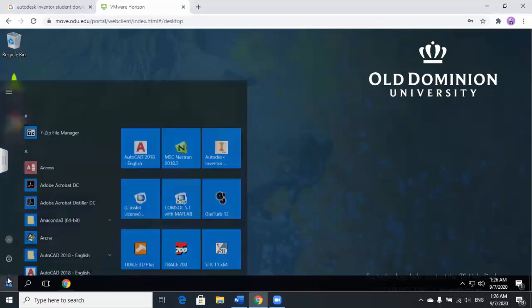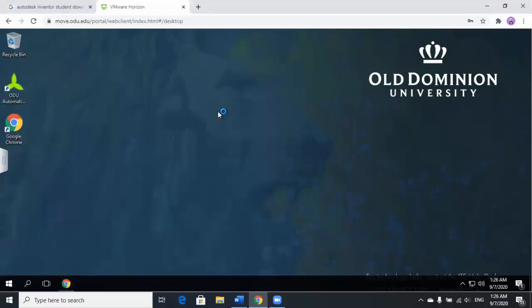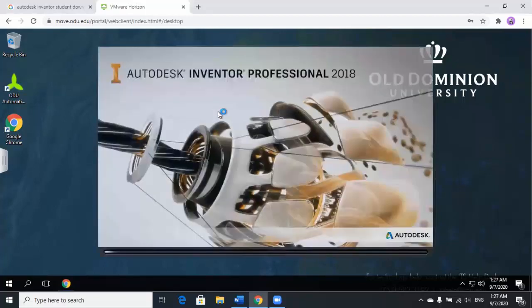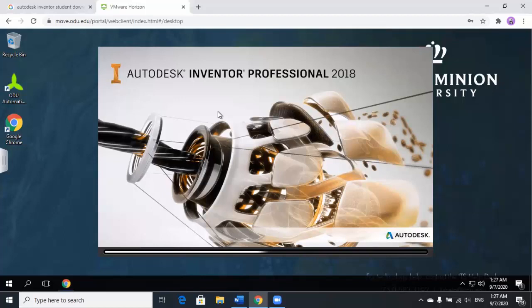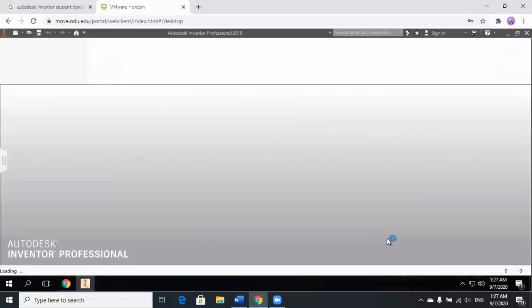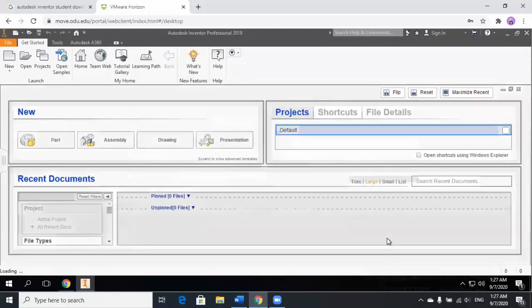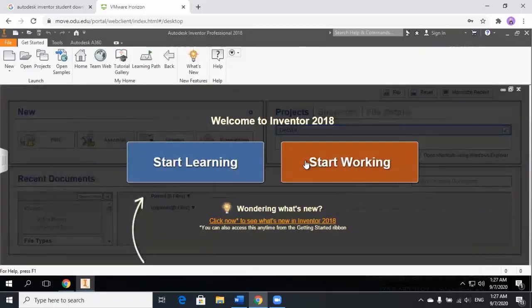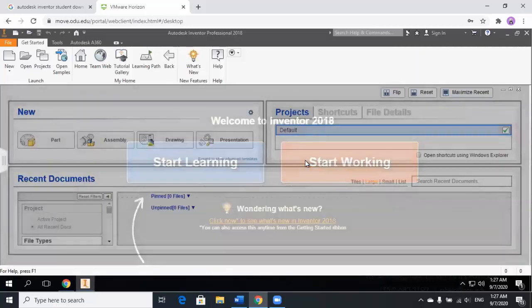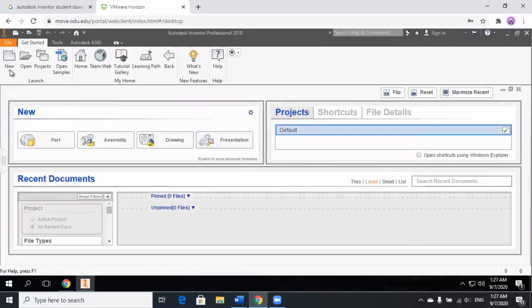So let's start. I will open Autodesk Inventor. And once it starts, it will ask me what kind of units do you want to use? If you take a look at the homework, I'm using inches. So the basic rectangular shape will be 3 inches by 2 inches, and I will extrude that by 0.375. So basically that will be the first box that I will do. And then I will drill one hole in the center, and then I will drill 4 other holes, and then all I have to do is some chamfers, and then I'm done.